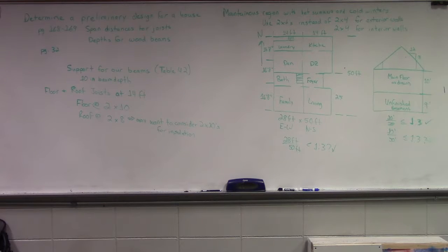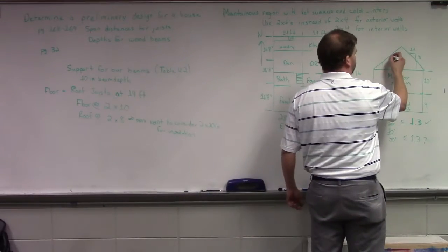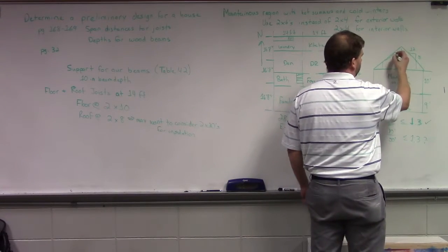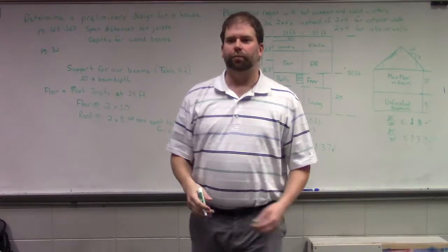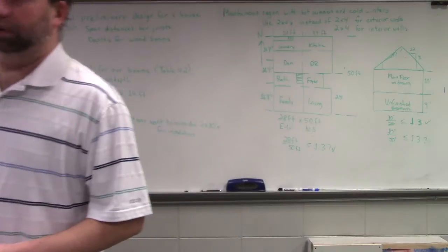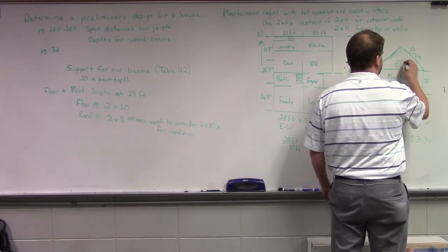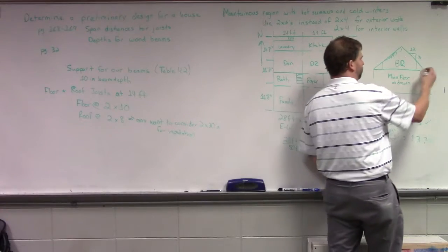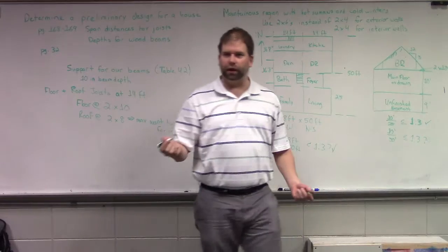Steve? So the way it's drawn, there's a bedroom in the attic, so to speak. So the joist that they're talking about for the roof joist, is it the floor of the attic, or is it the roof? True roof joists. I want to clarify what they're talking about above that bedroom. Which would bring me back to the 14-foot span. So if we're putting a bedroom here, this is still going to be a floor joist, 2x10, because that's a floor joist, right?